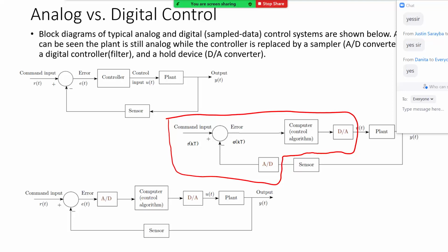The other thing, in order to be able to feed that signal and process it on a computer, the signal has to be quantized, which means I'm going to have a signal that could take on an infinite number of values, and say I only have, for instance, 6 bits to represent the signal, or I can have 8 bits to represent the signal, and therefore I might have 128 or 256 levels, and that's all the levels that the signal is allowed to take.